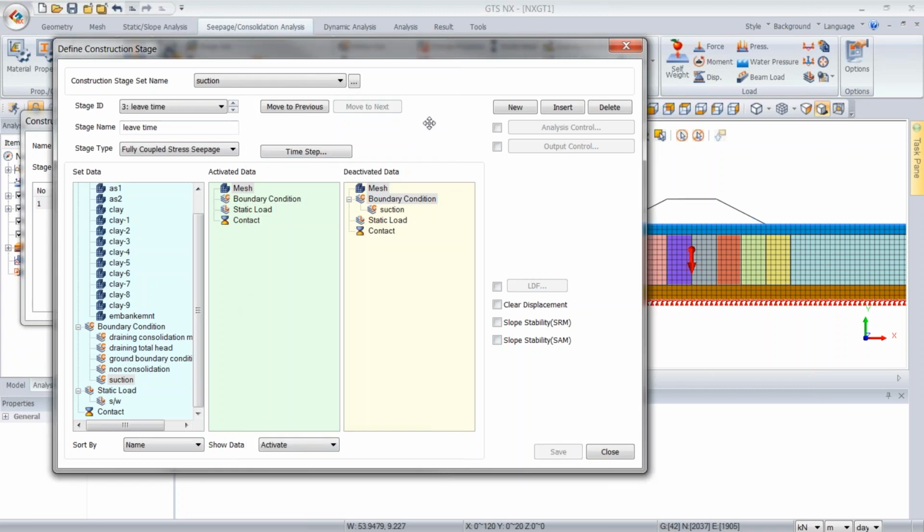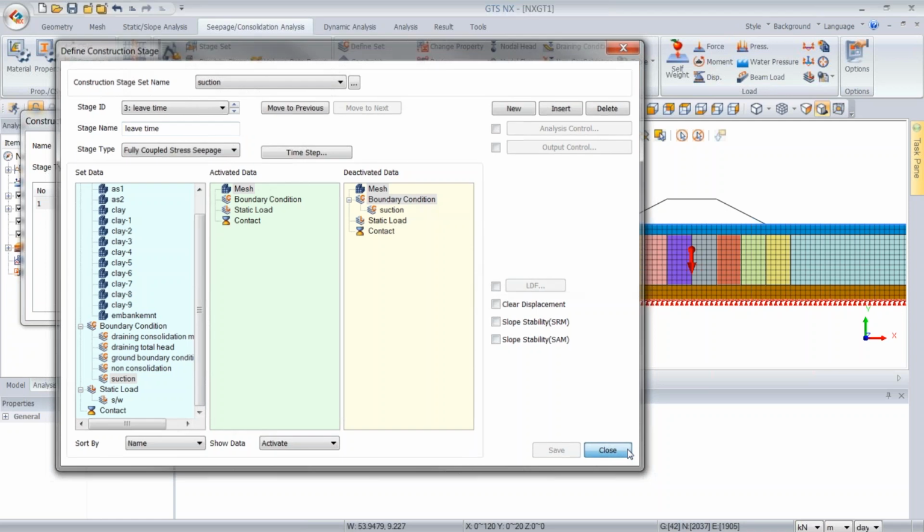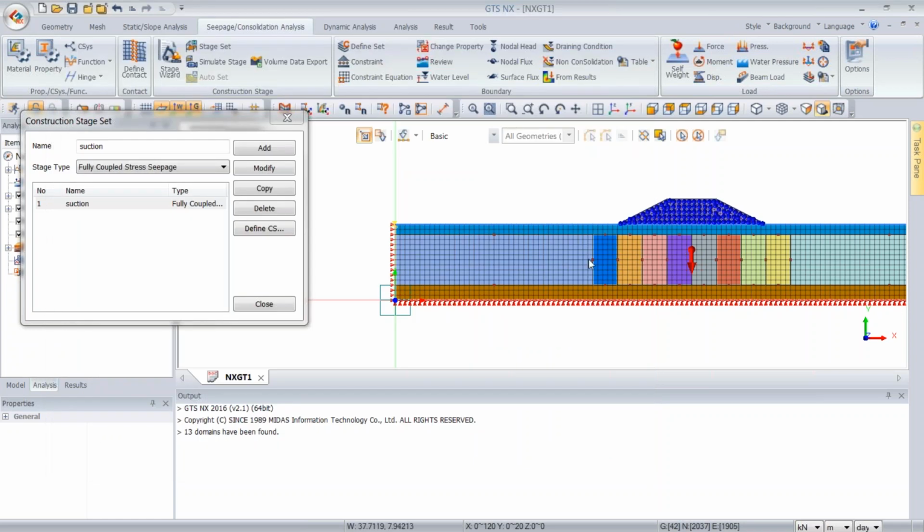So this is a very simple analysis, and so hence it only takes three steps. Basically, we're using a boundary condition, a drainage suction boundary condition, to create a settlement, a compaction of the soil. And we want to compare that versus not having that drainage boundary condition of suction, but just having the weight of the embankment itself. So we could actually just go ahead and create a whole new, define two other cases, each with the same 3 stages, one by one manually.